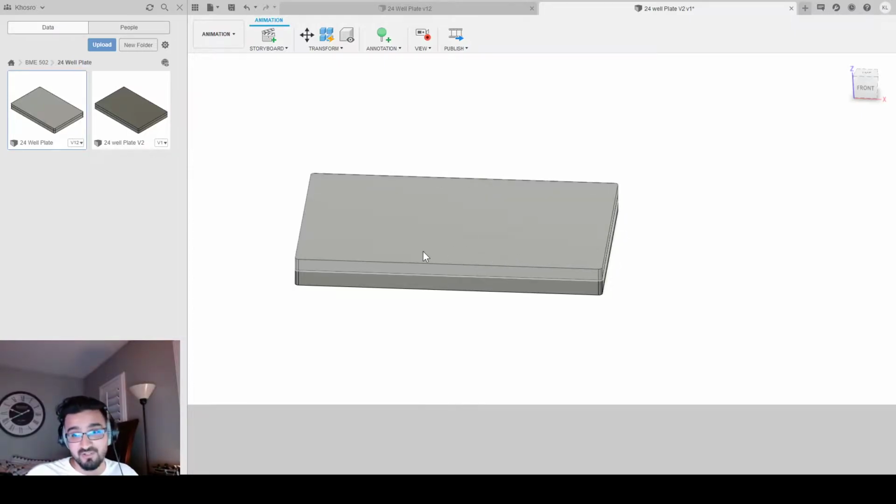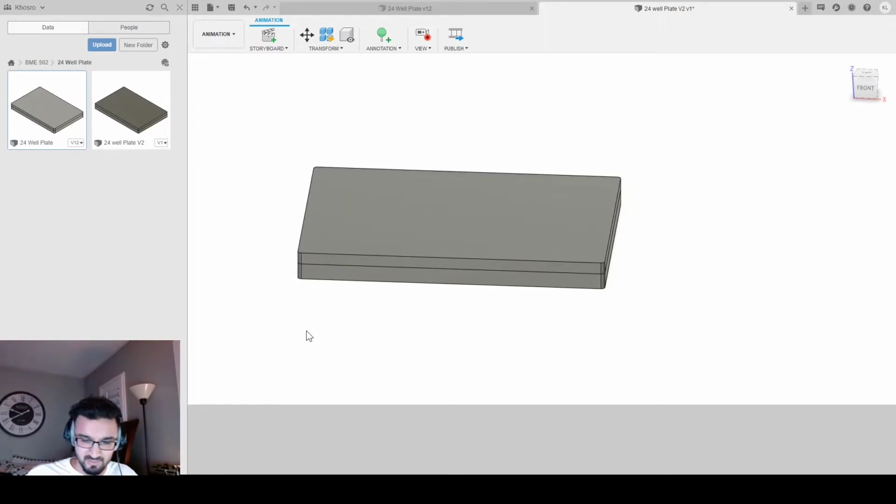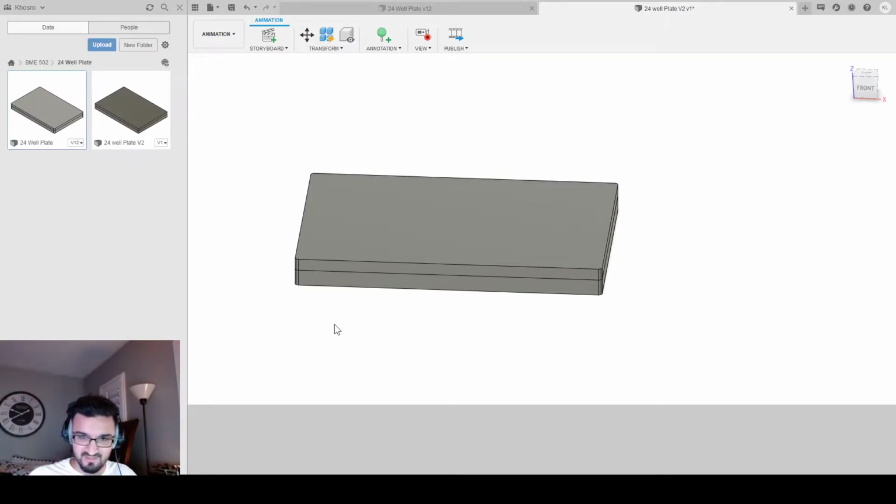Animation, however, can be very cool in Fusion 360. So here we have, let me delete that. Here we have our scene, essentially, our timeline, right? So anything you do with the record button activated, this little red thing activated, it will record what you're doing and put in a keyframe.